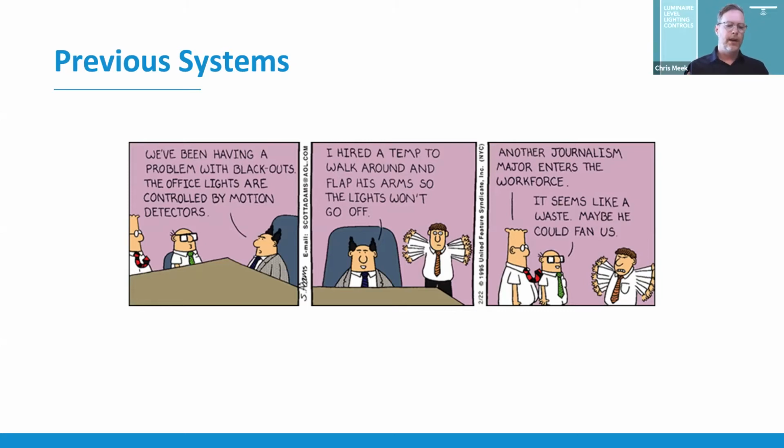The other challenge is associated with step daylighting systems, where all of a sudden there would be sufficient illuminance in the space, and the electric lighting, without warning you, without any input, suddenly de-energizes because there's sufficient daylight in the space. And from a specifications or performance standpoint, that might be exactly what the system should do based on the way it's programmed to operate. However, your eyes have adjusted to the light levels in the space, and when the lighting de-energizes, even if it's meeting set point, it's going to be perceived as dark. That's because the human eye does not adjust as quickly as the sudden light reduction that happens for daylighting effects.